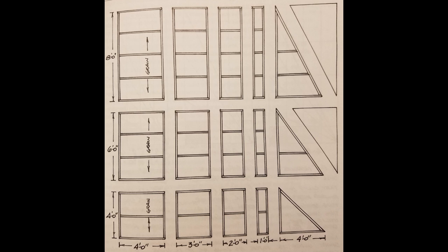Here you have a wide range of selections of your typical type. They typically do not ever exceed 8 feet in length, simply due to the fact that a standard sheet of plywood is 8 feet long by 4 feet wide. So that's why you'll typically build a lot of your stock platforms no greater than 4 foot wide by 8 foot tall. When you're also using plywood, you also want the thickest type due to, again, its strength